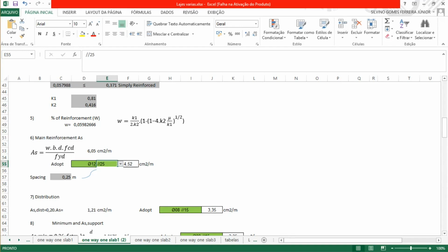So this is why I was using 12 here, and I prefer to use spaces of, it's not enough, so I have to go to space of 15 cm, and here it's 6. Spaced by 15 gives me 7.5, but if I lower here it's not enough, the steel. Oh, as we can see, it's not enough here, the steel, so this is why I'm using 12.